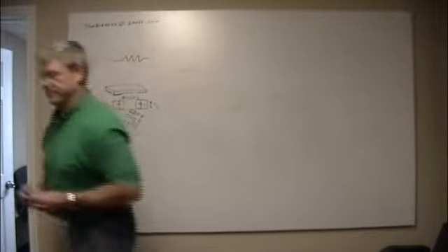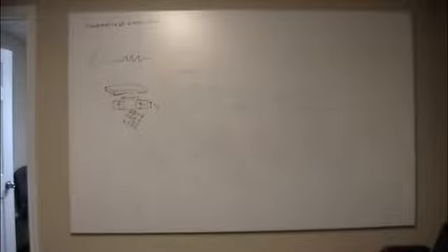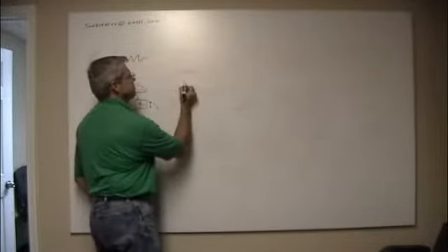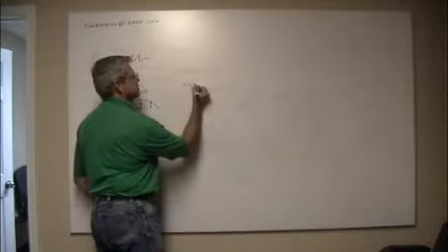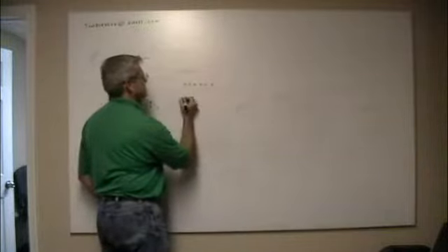So I'll bring this up here because I don't know if you people at home can see it. So you see my finger. I bent the back two leads, but each of those pins, this is what's called a through hole component, they're each 100 mils. A mil is 1,000th of an inch, so 0.1 inch. And when you look on your circuit board, you'll see these little annular rings, holes, vias. 1, 2, 3, 4, 5, 6.